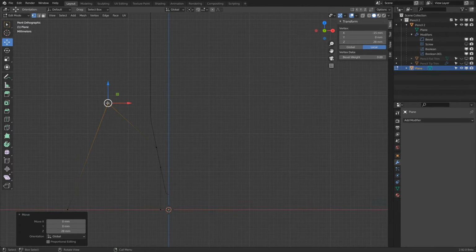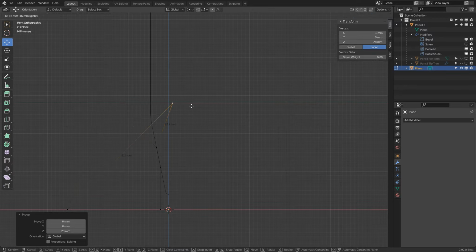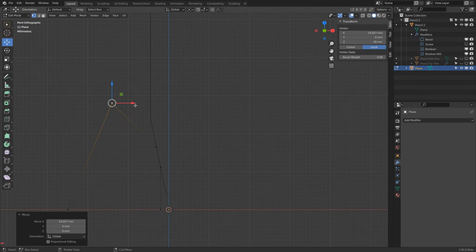Now along the horizontal plane, from the z-axis, so from 0 to the left, it should be 17. I click on the red arrow, snap it to the center, bring this over, and then here type in -17. Very good. So you see, I used the grid very quickly to do some basic adjustments and create very precise geometry.